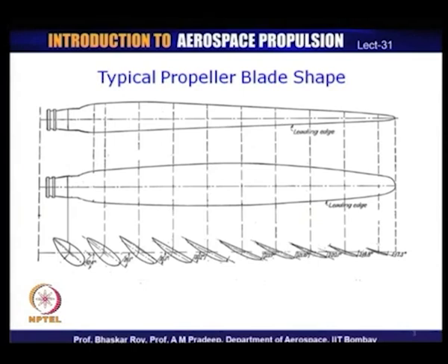So, the performance at that section would be representative of the entire propeller. If you calculate the elemental thrust there, that would be an average elemental thrust representative of the entire propeller. That is how propeller design is proceeded: you start off with a representative blade section, which is not at 50%, but normally at around 0.75 R.